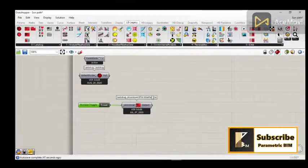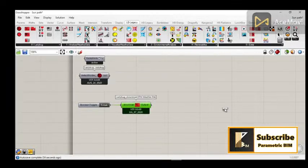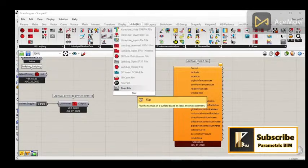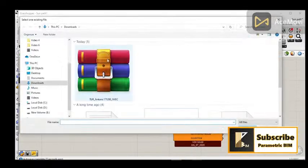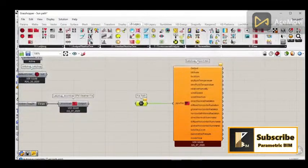I will go back here, and then I am going to import the EPW file. Once I bring the Ladybug import EPW component, I can now bring a file path and connect it to the EPW file. Right click and select one existing, go to the downloaded file and select it, and now it works.